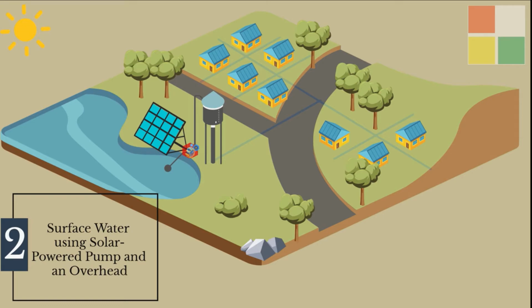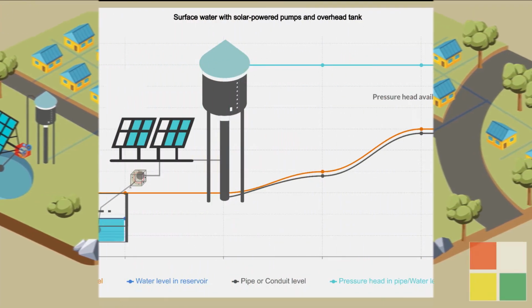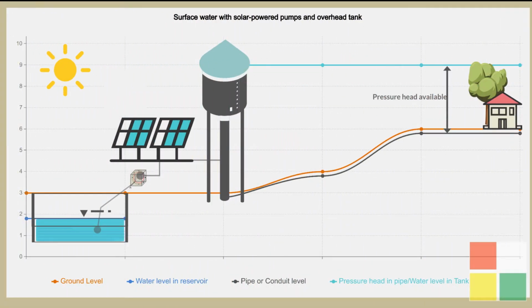If the pumping system solely depends on solar energy, or water demand fluctuates during the design period, or a combination of both, it is highly advised to construct an overhead tank, as it stabilizes the water pressure and ensures availability of the water in the system.